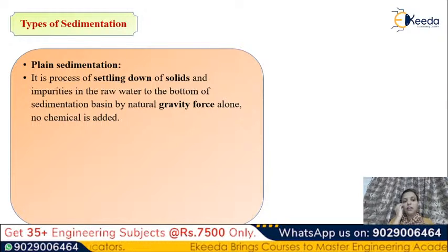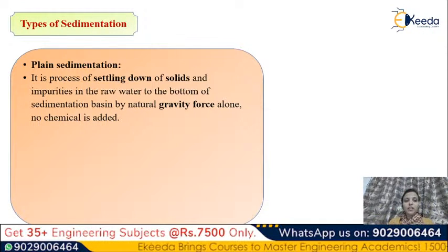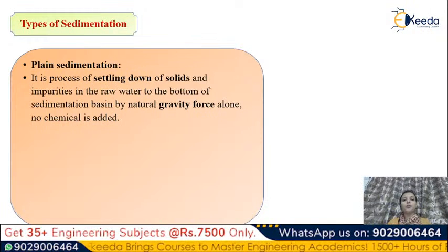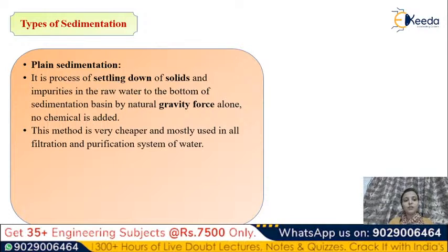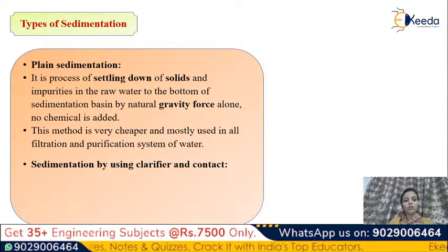In plain sedimentation, it is the process of settling down of solids and impurities in raw water to the bottom of the sedimentation basin by natural force alone. No chemical is added. Without adding chemicals, sedimentation takes place. That sedimentation is called plain sedimentation. This method is very cheap and mostly used in all filtration and purification systems of water.